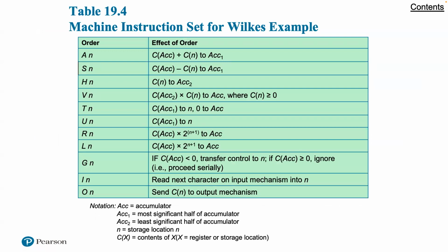The control unit seems a reasonably simple device. Nevertheless, to implement a control unit as an interconnection of basic logic elements is no easy task. The design must include logic for sequencing through microoperations, for executing microoperations, for interpreting microcodes, and for making decisions based on ALU flags.